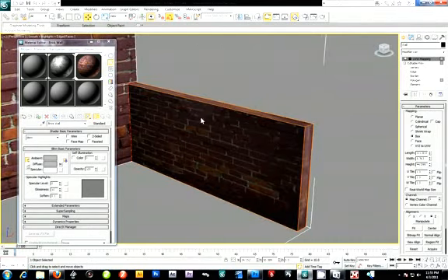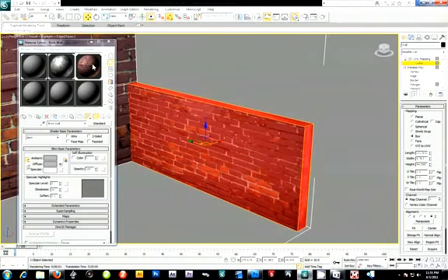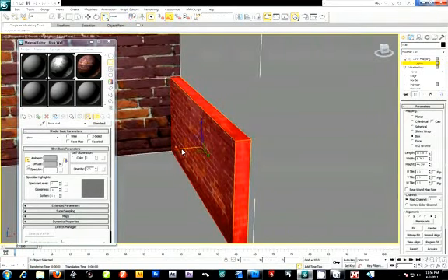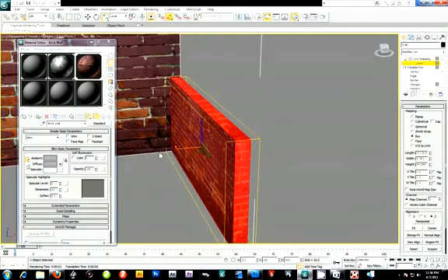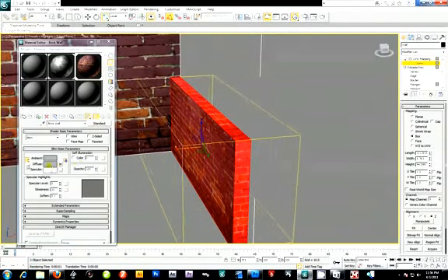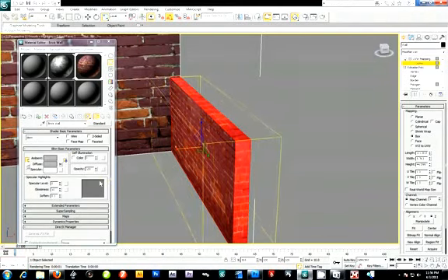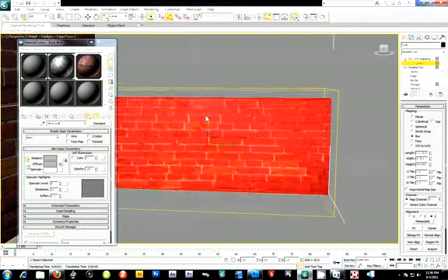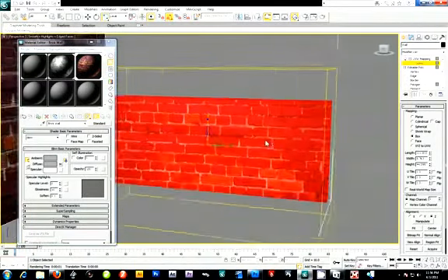Alright, so with the UV map on there, let's drop it to the gizmo here. I'm going to take my scale tool, and we can play it safe and go on its local axis, and the rule is, always scale the gizmo bigger than the geometry itself. And as you can see, look at the sides. The pinching is now getting straightened out a little bit. That's usually what you want to do. And if you want, you can actually stretch it this way. Alright, that looks pretty good.